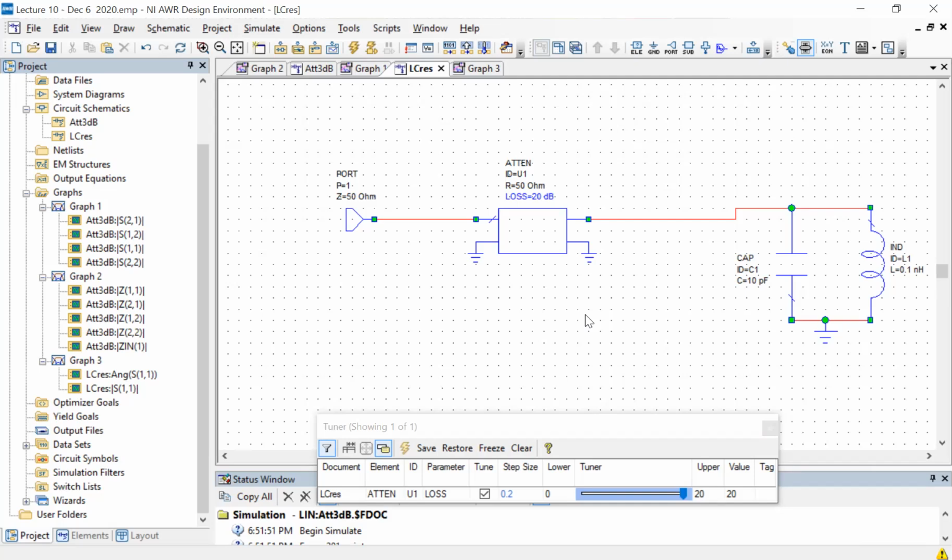But if you really want to know the full situation, the full scattering matrix, you can't get this. And even in that case, there will be small errors, because reflections can turn into transmissions if things are not matched up correctly. So a lot of this you will see from experience as you measure these things. Okay, yeah, got it.